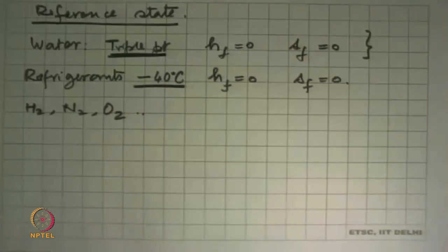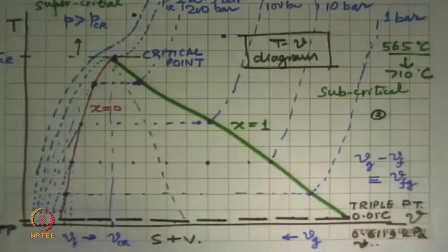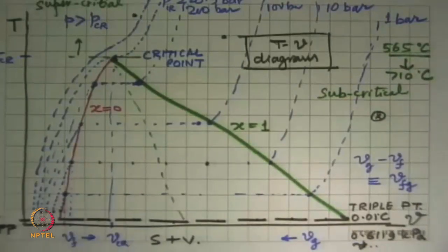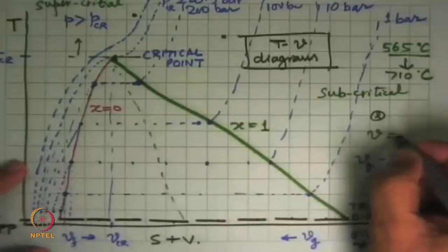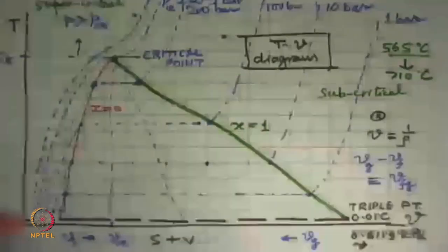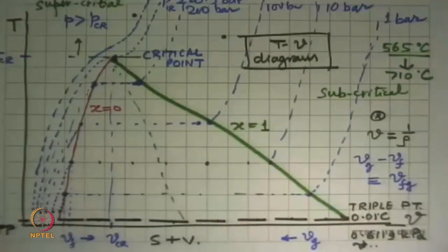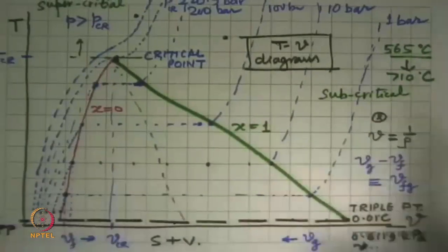Then there is another question. Why does specific volume of liquid decrease as we increase the pressure? Okay. The question is, why are these points going like this when we increase the pressure? If you look at it the other way, by looking at density, when you take water and compress it, its volume goes down. It becomes denser, so density increases. And specific volume is 1 upon density. So when you increase the pressure, the density has increased, and the specific volume has decreased. That's the reason.